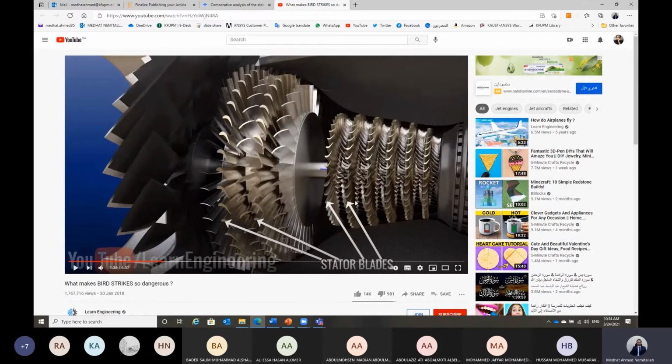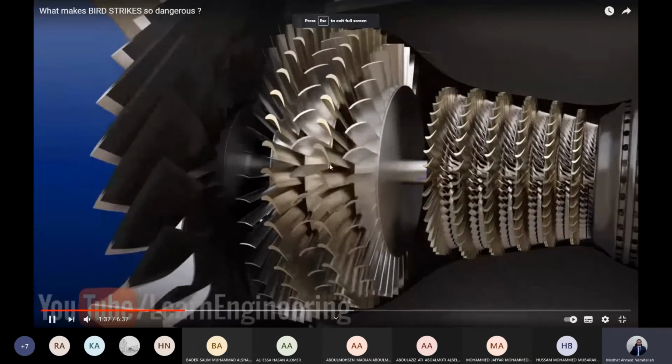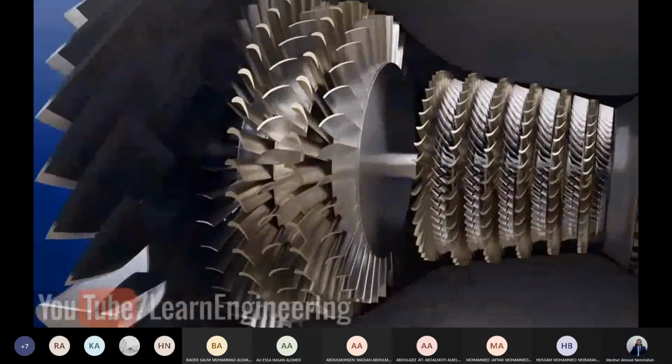But look here, the compressor consists of a fixed blade followed by a row of moving blades. The function of the fixed blade is to direct the flow. But let's look at what will happen if the angle of attack in this case is changed. The rotor blades have an airfoil cross section.